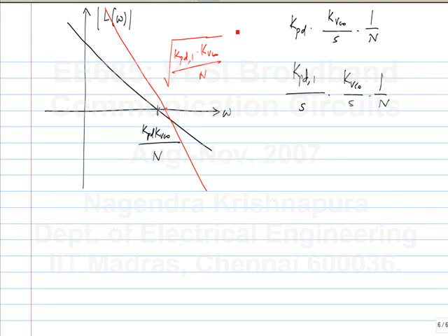It is this, and this is clearly unstable according to the criterion we just stated, since the magnitude response has a slope of minus 40 dB per decade at the unity gain crossing. This will give you a very high gain at DC. This extra infinite gain at DC is what we were looking for to increase the lock range, but it doesn't work. It also gives you high attenuation at high frequencies, but again there is a problem.